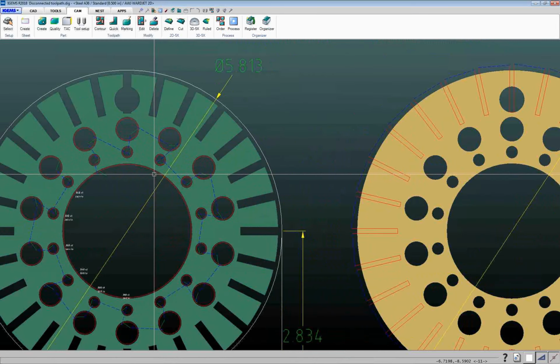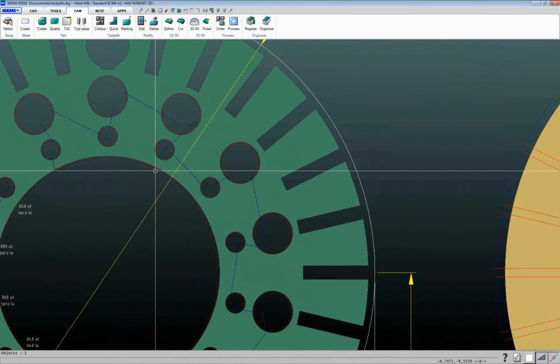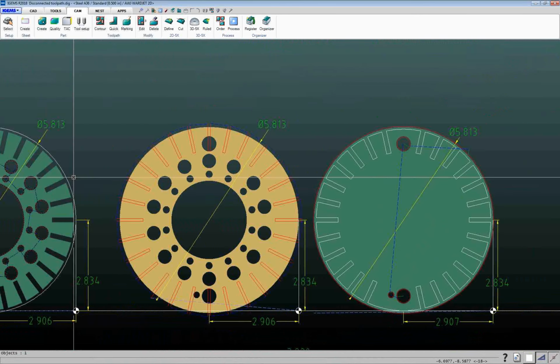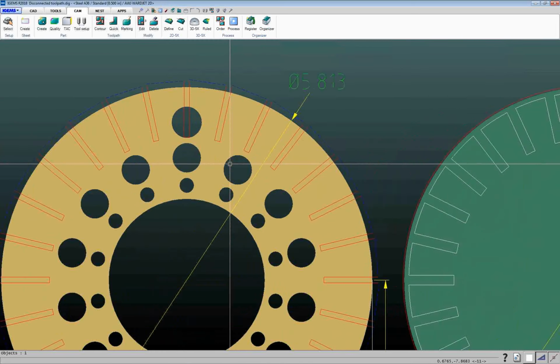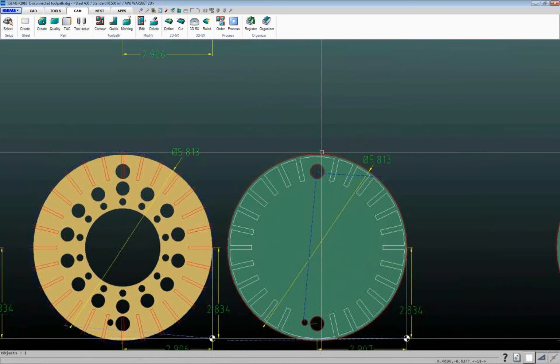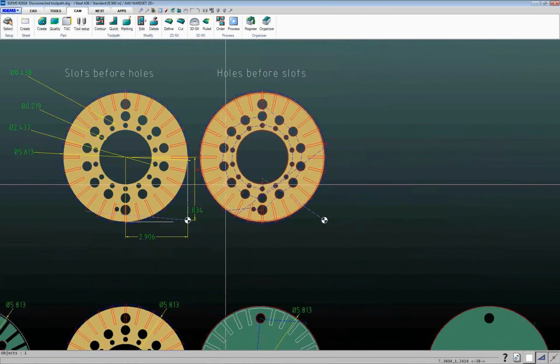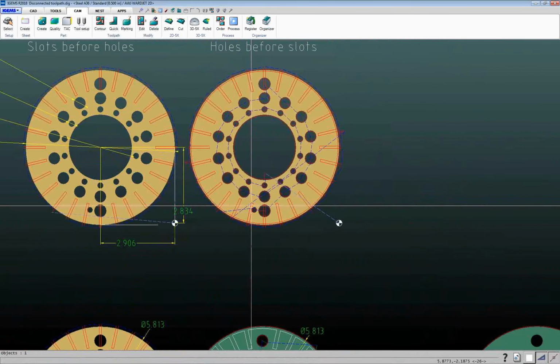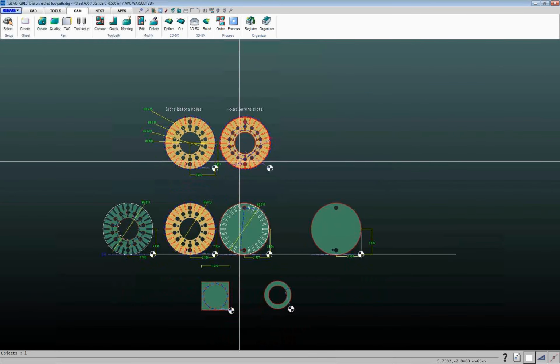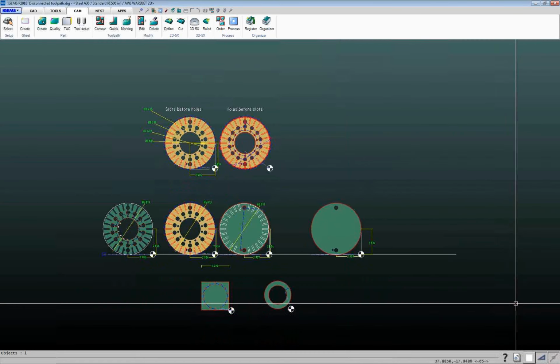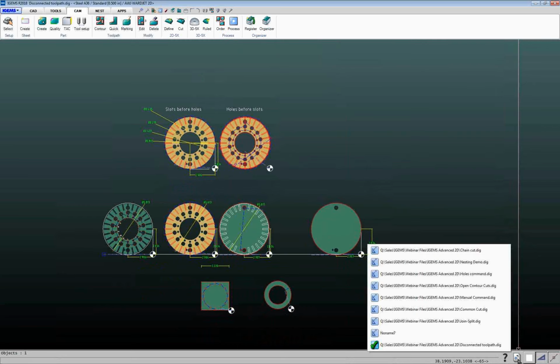So I ended up making multiple toolpaths where I did this as a 2D toolpath. This one here I did as a 5-axis toolpath in the 3D 5-axis module. And then this one here was also a separate 2D toolpath. In the end, I ended up combining them all together into one part. So that's one rare circumstance where I found that command to be helpful.